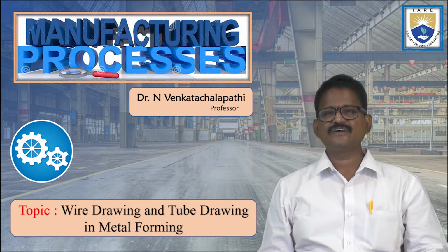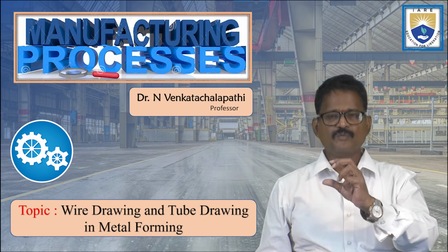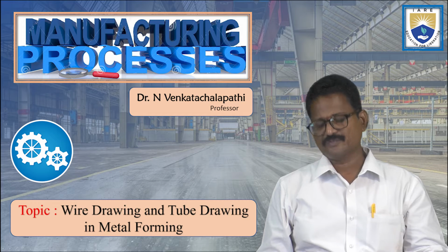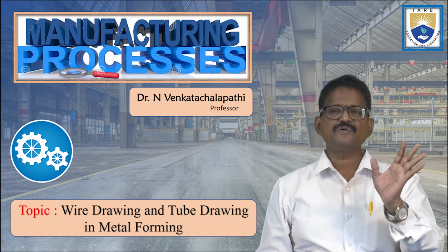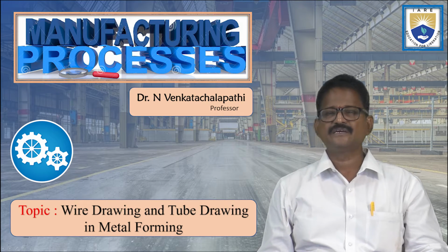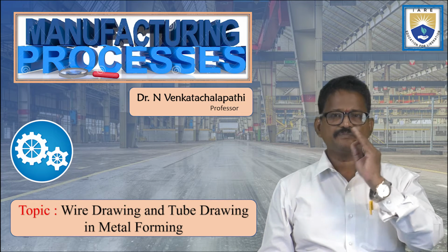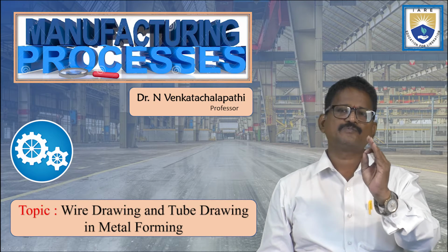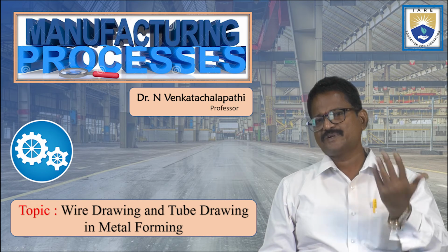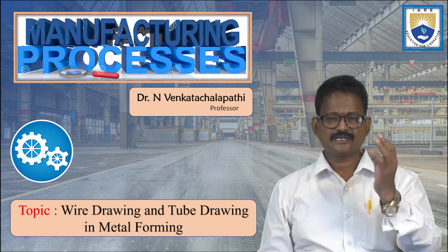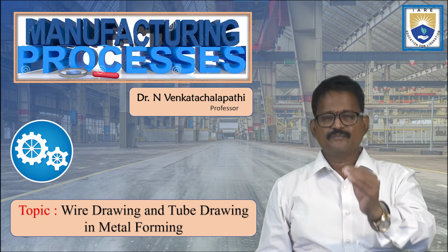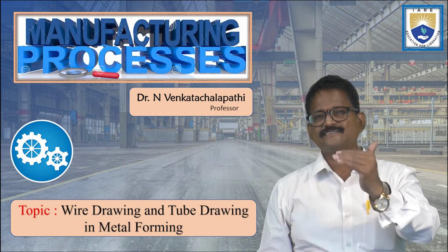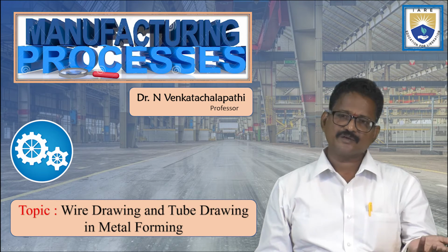So what is the required shape of the component to be produced in this metal forming process? In this process, the main thing is that the wastage of material is minimal or negligible. This metal forming mainly depends upon another important term called hot working. What is meant by hot working? In general, hot working can be defined as the process of heating the metal above the recrystallization temperature. We call it a hot working process.